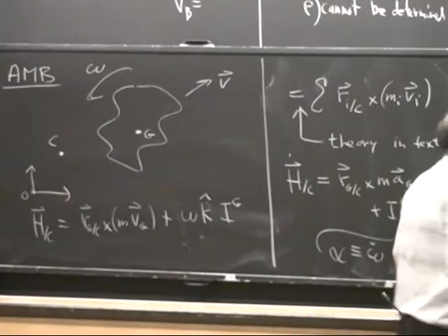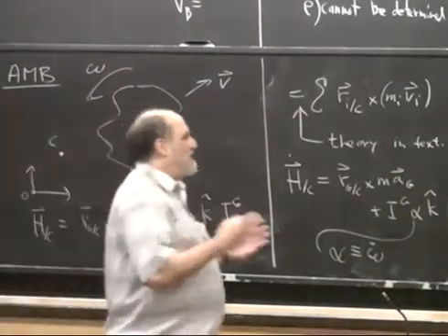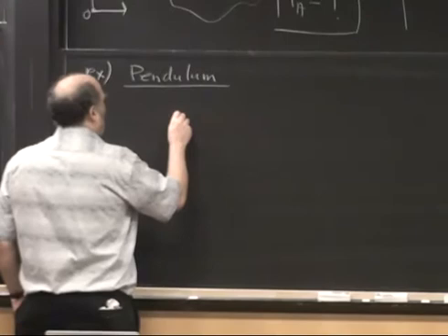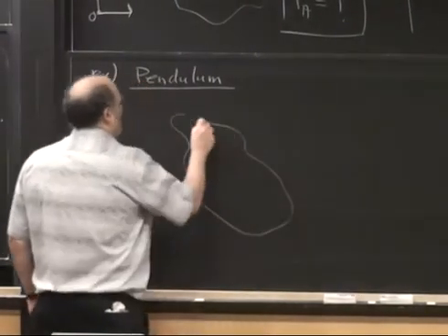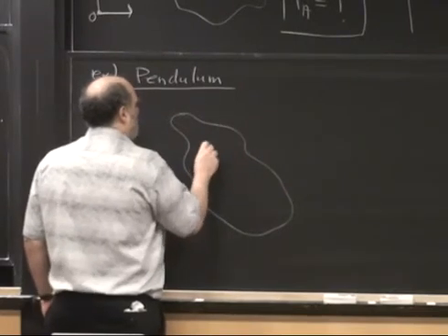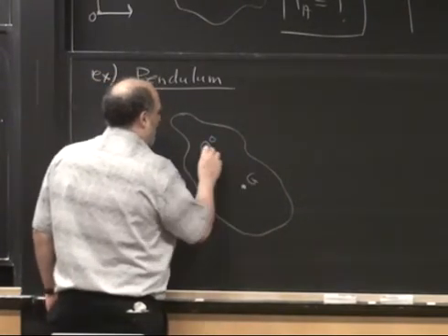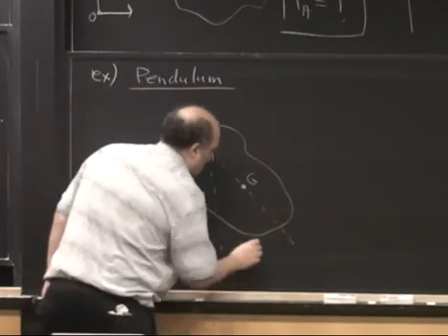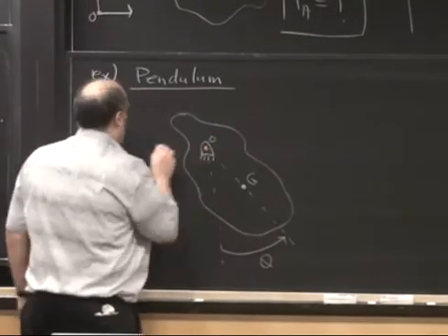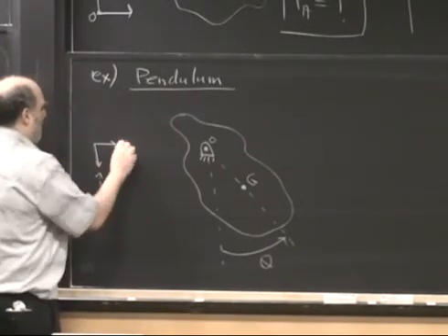And just like you had to learn the point pendulum inside out and backwards, you have to learn this so-called physical pendulum or rigid object pendulum, not point mass pendulum. You have to learn this one inside and out sideways also. What we're imagining is we take some rigid object and we hinge it about some point here, and we'll call this hinge point O, and the center of mass of this object is, say, here. Let's call this G, and we'll keep track of where this object is by paying attention to the angle of G relative to vertically down, and we will pick a coordinate system that has I down and J to the right.